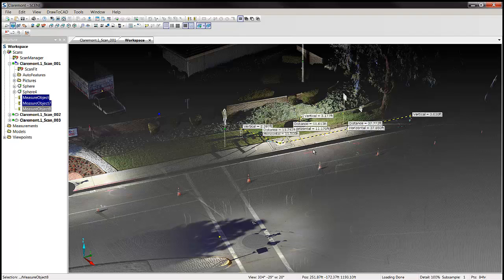So that would enable you to find a feature that perhaps was lost because it was covered over, or during construction something was removed. We can take any of these points, we could actually pull it from the curb here. We can choose anything that we want, anything that's still visible, we could actually pull a point and find that covered up manhole.